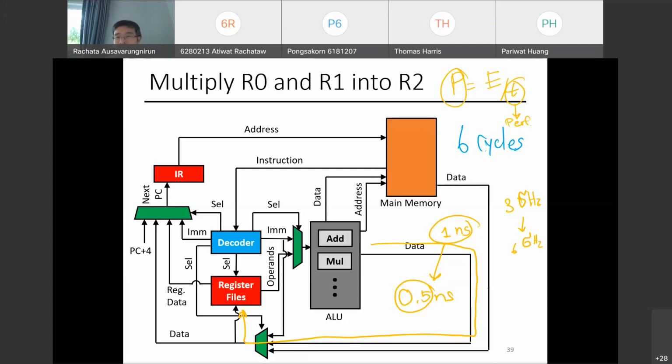So if T goes lower, but P goes higher, can I have the same energy output? I mean, possibly, right? Because your energy is P multiplied by T. If I overclock, P goes up, power goes up, performance goes up too. So time goes down. It takes less time to finish my program. Energy is unknown. It can go up or go down, right? I'll give you one example.